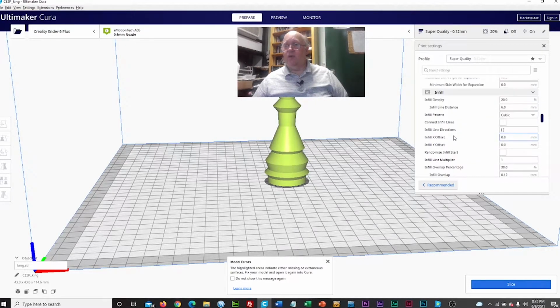So the only other one we have to think about is Infill. That is the amount of empty space the program leaves inside the printed object. If you have 100% infill, that means it's going to fill the object in a completely solid fashion. If you take it to 20%, which we'll leave it at, that will create a honeycomb pattern of airspace on the inside. It saves time and plastic. If you want a nice solid piece, you can leave it at 100%, but expect that to take longer to print.